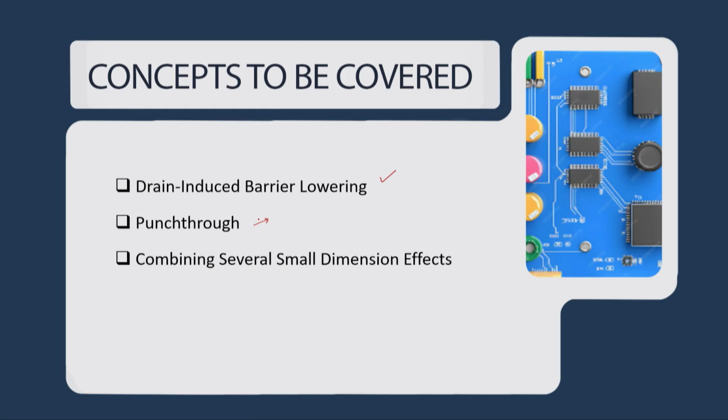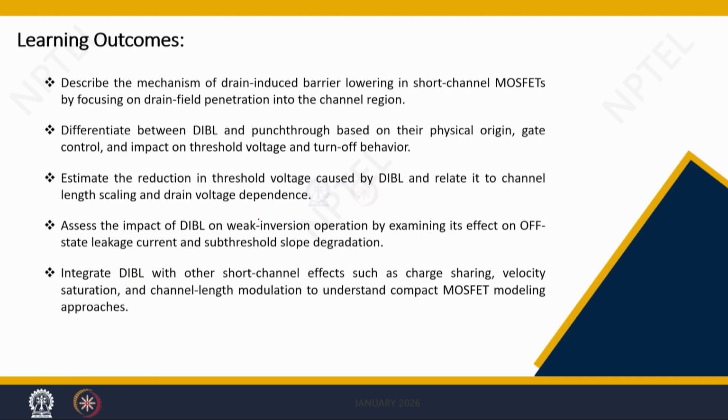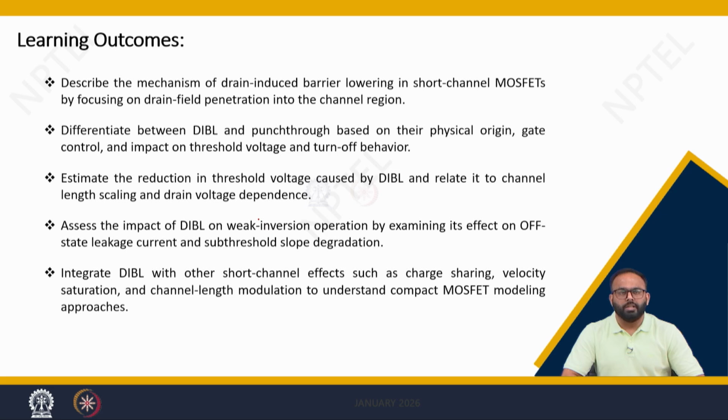for long channel MOSFETs. So, these are the learning outcomes of this lecture, which help you to understand the mechanism of drain induced barrier lowering in short channel MOSFET by focusing on drain field penetration into the channel region. We will also discuss the impact of DIBL on weak inversion operation by examining its effect on off state leakage current and subthreshold slope. We will see the impact of punch through in short channel devices.